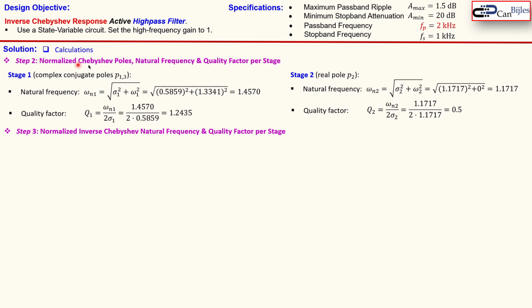So you get 4 minus 1 in total times pi over 6. That will then result in 1 over the cosine of pi over 2. But the cosine of pi over 2 is 0. That means the zero frequency will be at infinity. So we will have 2 zero frequencies, one at 1.1547, the other one will be at infinity in this case.